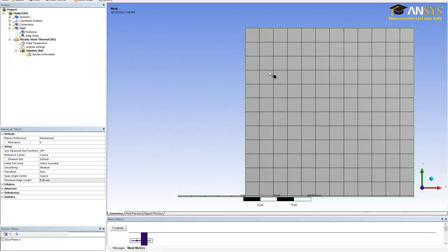Another refinement that you can do is simply by going into the sizing option when the mesh tab is highlighted. You can set the relevance center to medium or fine, which will make the mesh smaller and smaller. The element size you can set to say 10 micrometers, something like that. Change the smoothing and all the fine. There is a ton of stuff you can do here.